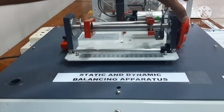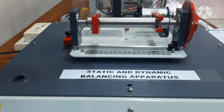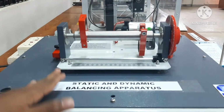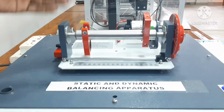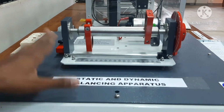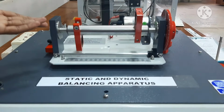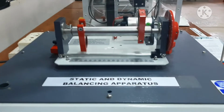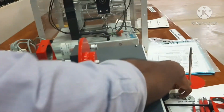To check the dynamic balance of this two mass system, we have to rotate it. First we have to rotate it and see whether it is vibrating or not. If this two mass system were balanced, that would mean there is no couple or twisting moment in it. Let's see by rotating this two mass system whether it is vibrating or not.